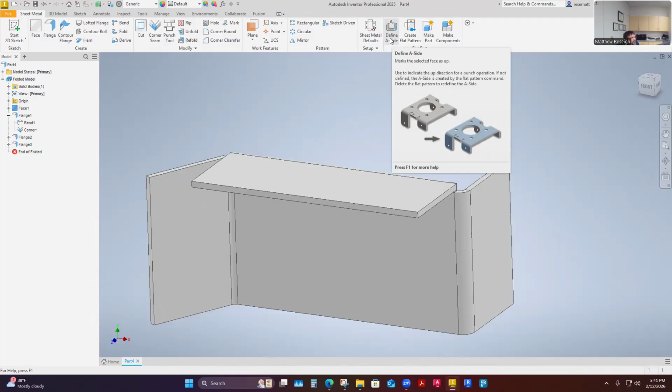What it does is, when we move sheet metal around to put it on laser tables and plasma tables to cut it, there can be some damage to the sheet, especially as you lay a sheet against the laser table. There's going to be a side against some fingers in the laser table, and if you slide it around, you can scratch the part. Some materials are more prone to scratching than others, and scratching can be really detrimental in some highly critical areas.